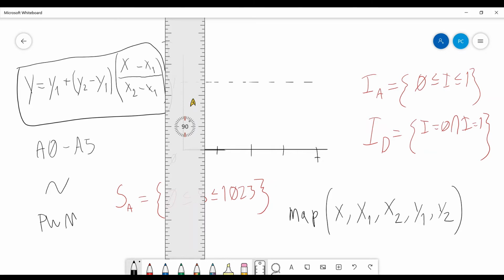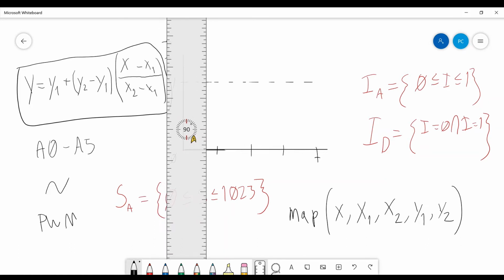Now, when it comes to how long this works, the PWM, the pulse width modulation, what it does is that it gets the voltage, and then it actually turns it off and back on for a specific amount of time. You see, these little increments, those are an infinitesimally small amount of time, and the voltage is on for a percentage of the time. You get it?